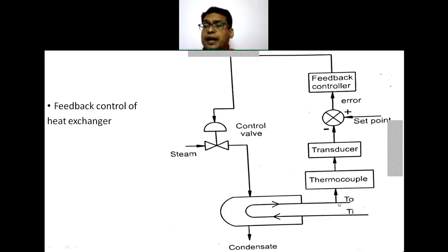In general, feedback is related to the measurement of the outlet process stream. Feedback specifically talks about the measurement of the outlet stream. That is why every time we measure whatever entity we want to control: in the case of a heat exchanger, the temperature control. In the case of a distillation column, it can be either temperature, pressure, or composition control depending on the process requirement.